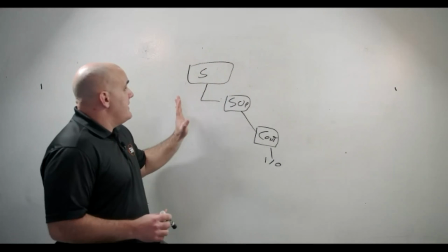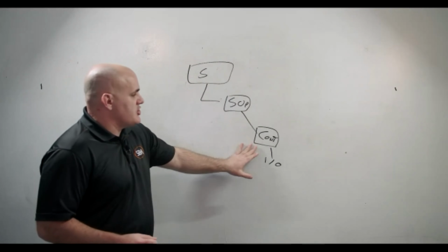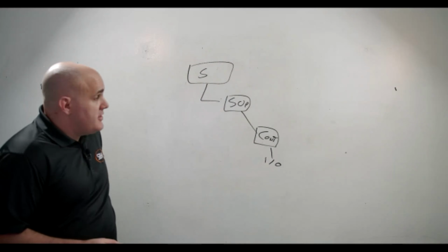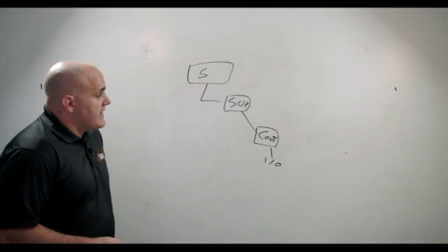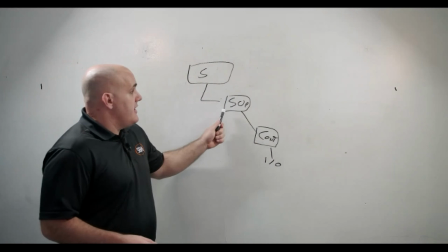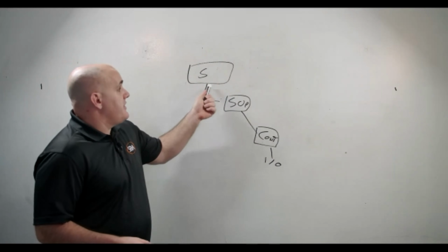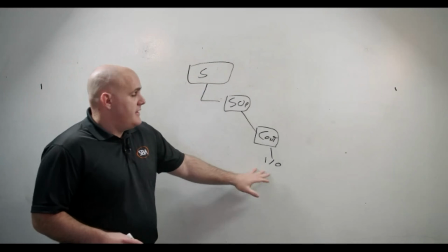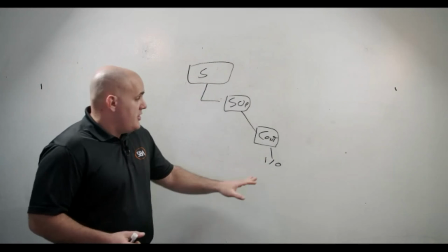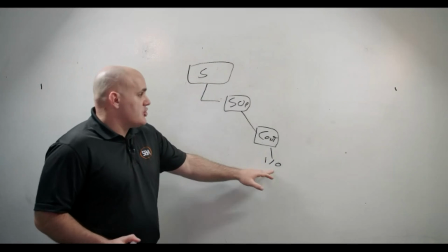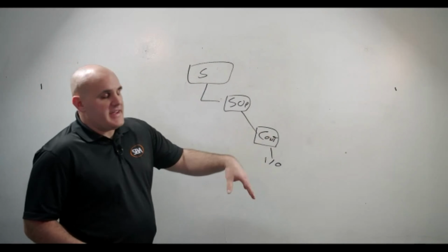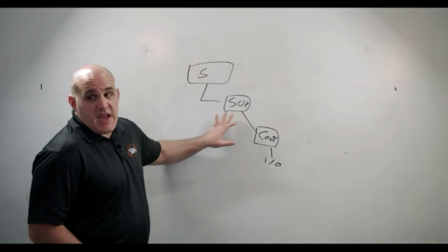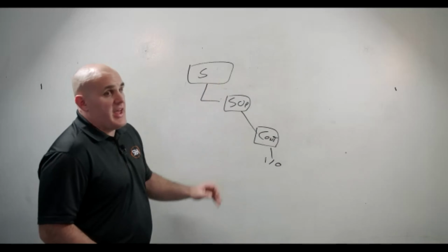Okay, so server, supervisory device, controller, IO. This can be an access control system. So access control system, you could have the door controller right here, the main access controller here, and then the server with the access database. And you can have your card reader and your lock. This can be a lighting system. You can have the ballast and the light controller or the light switch. You can have the controller on the ballast going to the area or zone supervisor, going to the lighting server.